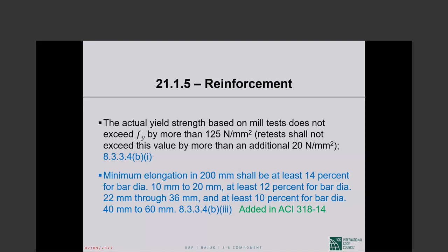That beam, stronger in flexure, will attract more shear force to itself in an earthquake. And we will not be correspondingly increasing the shear strength of the member, thereby making brittle shear failure more likely.